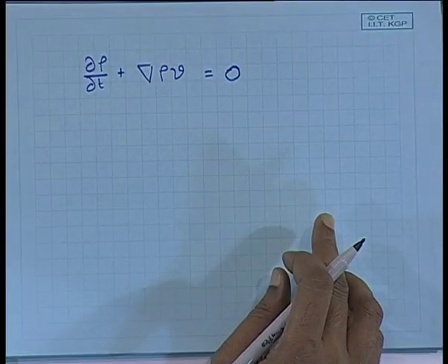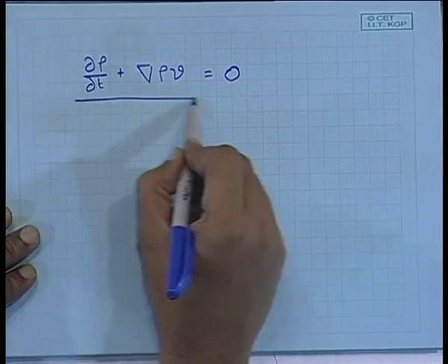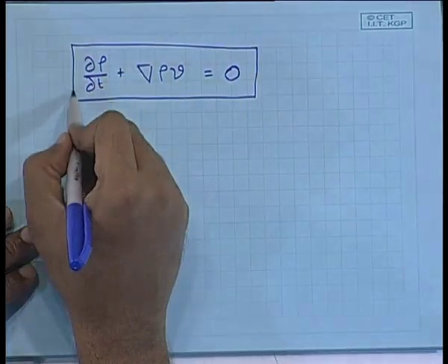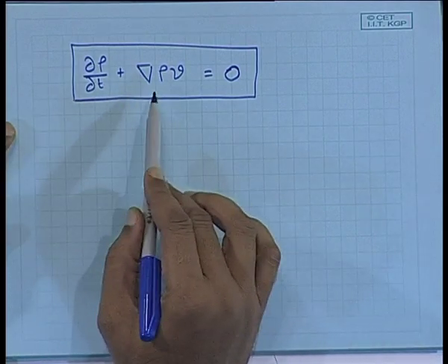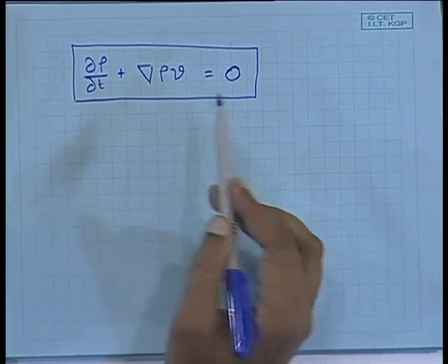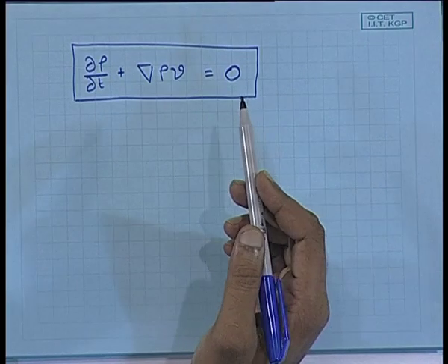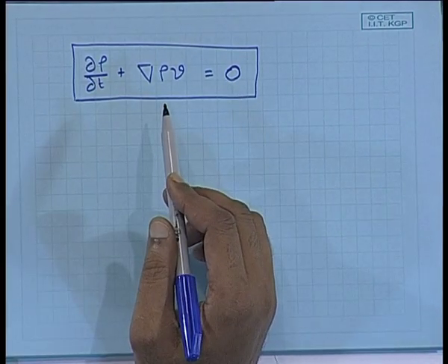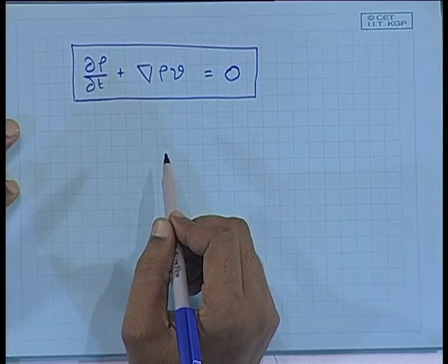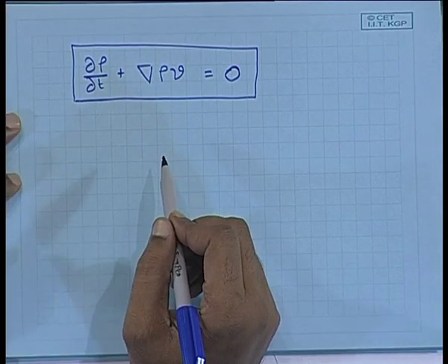So, if I come to this equation now, which is the conservation equation, does this look familiar? What is this? It is the equation of continuity for the whole mixture. So, it is consistent with what we have seen before in fluid mechanics, that if we consider the whole thing as one, then the equation of continuity can be applied.